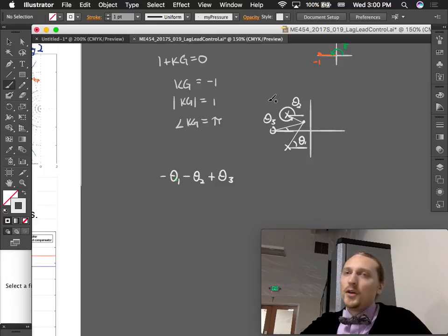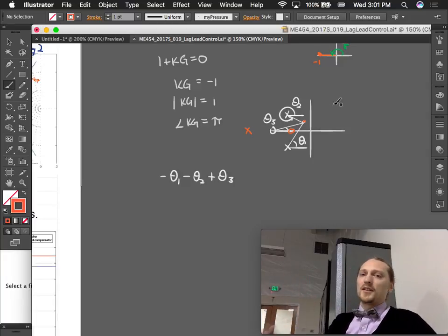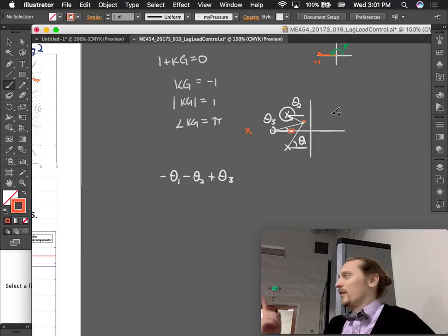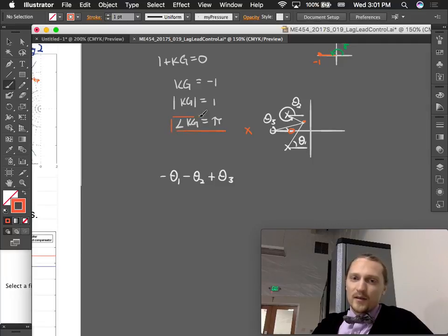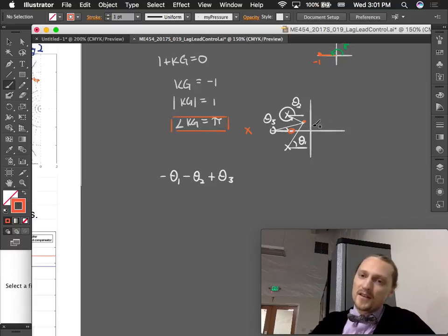In any case, you're summing these angles together. If I'm going to just place a new compensator zero, just slap it in there, and a new pole, these two are going to affect it. They're going to have their own angle contributions. The trigonometry problem you're doing is that you picked your test point where you want the locus to go through, and you get to choose where the zero and the pole are to make that happen. But you actually have two parameters to adjust, where the zero is and where the pole is separately, and you only have an algebraic equation that specifies one of those. So you have to arbitrarily specify where one of them is going to be. That's why we set that zero to -5, and then we can move the pole to be wherever it needs to be to make the root locus go through your test point.